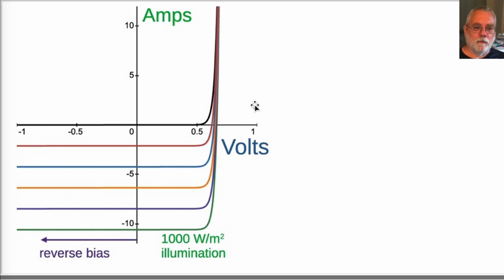Solar cells never operate in the upper right quadrant, with this convention for current. We will see later that solar cells are sometimes forced by load and partial shading to operate in the lower left quadrant, in which the solar cell dissipates power instead of sourcing it. Consider a solar cell with a current of -4 amperes and an imposed voltage of -20 volts, reverse bias.